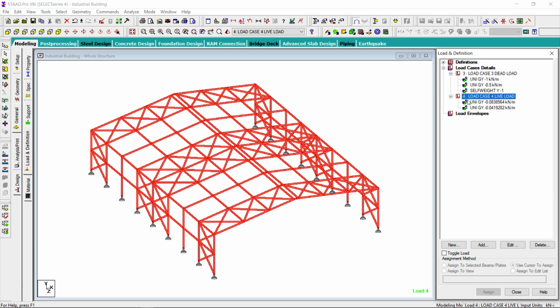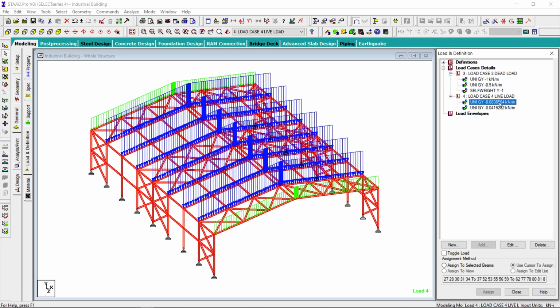Similarly, the live load on the roof is taken as 20 pound per square foot as per the standard, and similarly I calculated the area and multiplied by this load and ended up with such a small load on the beams.